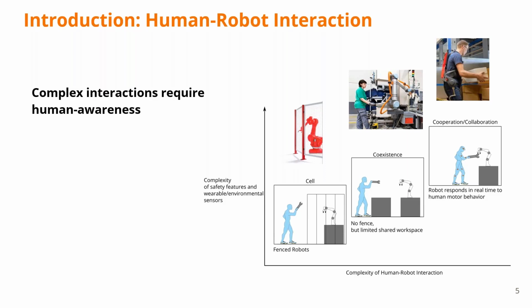But on the other side of the spectrum, if the human and the robot are working as a team in direct contact, the robot now needs to know the human status, which is something that is not trivial, possibly with sensors equipped on the human, such as for human localization in space or to measure the body posture. Only then will the robot be able to modulate its behavior to ensure not only the task execution, but also the safety of the task.